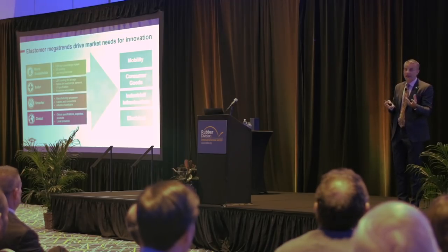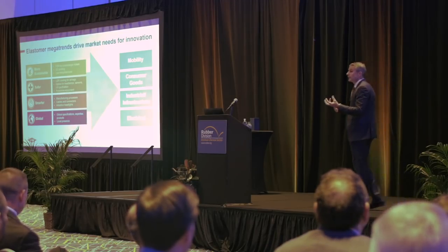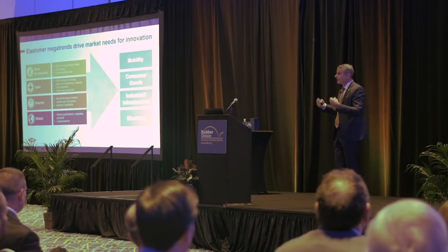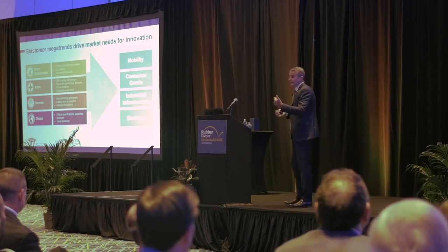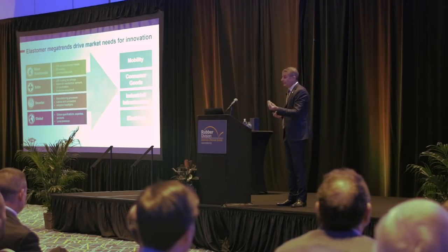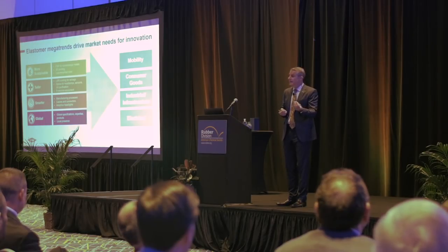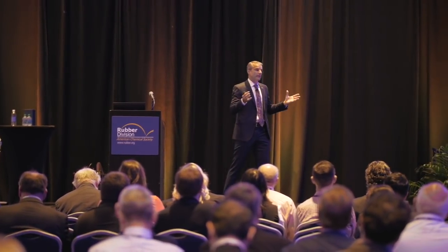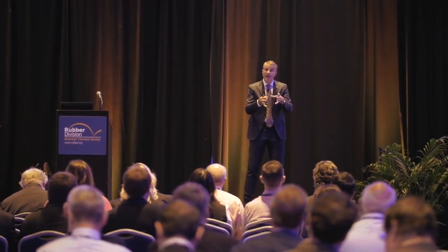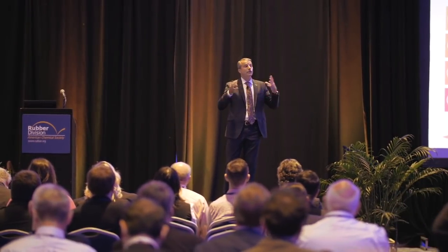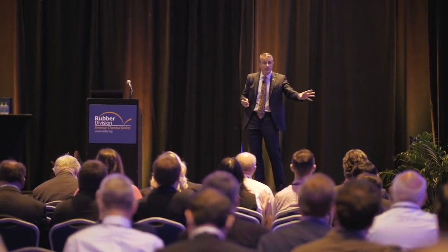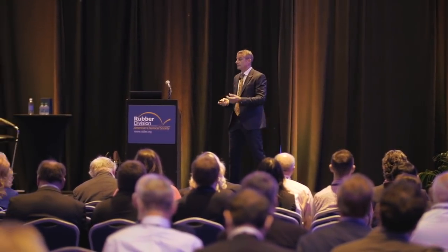Turbo technology is that. Turbo technology now requires materials, hoses that are exposed to very high temperatures. They have to be flexible, they have to last for 10 to 15 years, and they have to have fuel resistance. Now you get all this, right? So now you can get out of a 2-liter engine with a turbo what used to require a 4-liter V8 or something. By downsizing that engine, you get collateral benefits because you can down-gauge other parts of the car, so you get weight savings and fuel savings by just a more efficient engine.